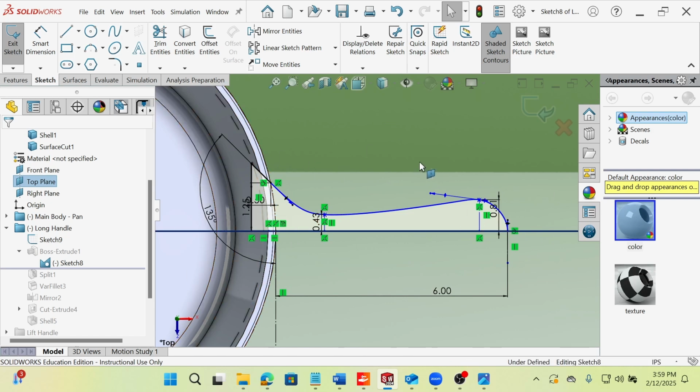So got a nice one single side of my handle, kind of drafted up, and I just used a simple spline and measured what I thought would be a comfortable handle width, divided it by 2. So I have a thin portion, a thick portion at the very back that I know I want to put a hanging loop in, so that's bulged out a little bit more. But nothing too specific about these measurements, just something I had tried, refined, and dragged these around a little bit till I was happy with the shape.